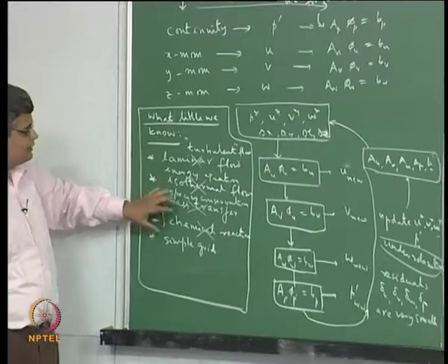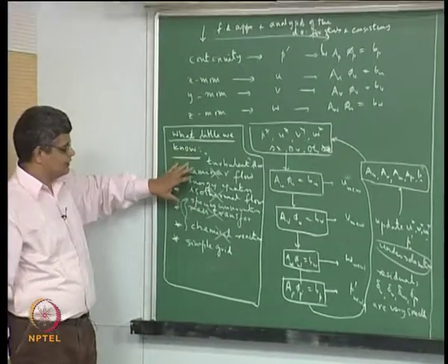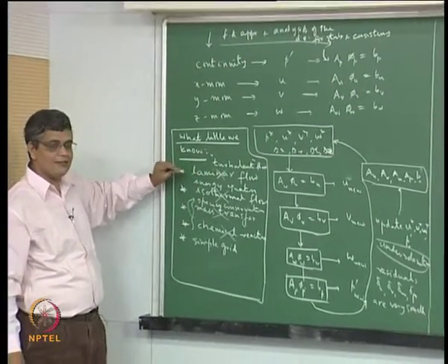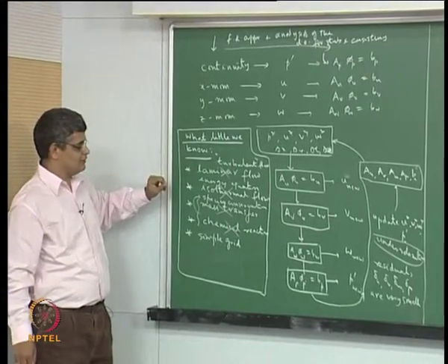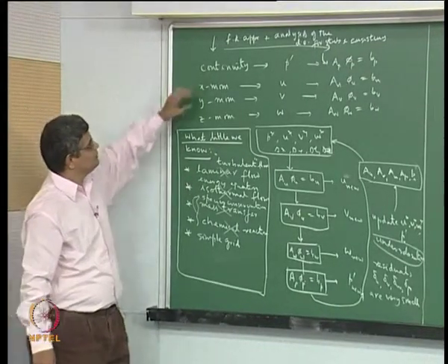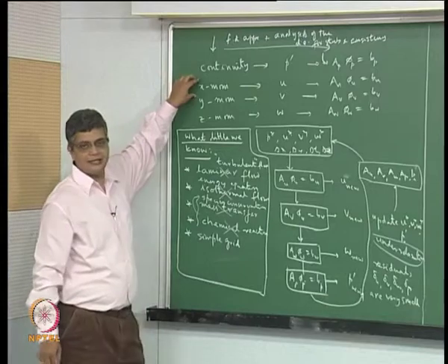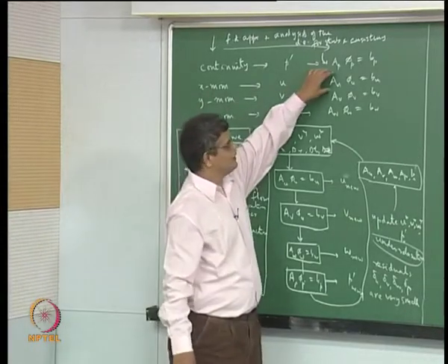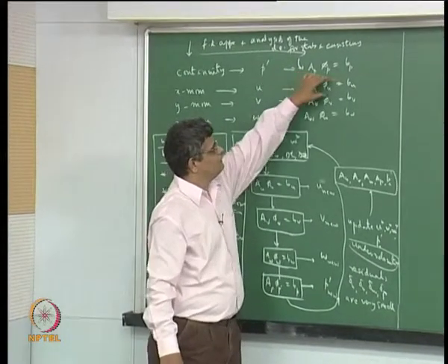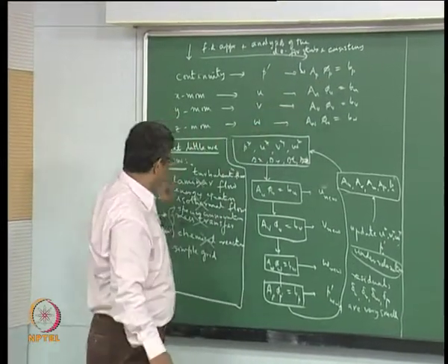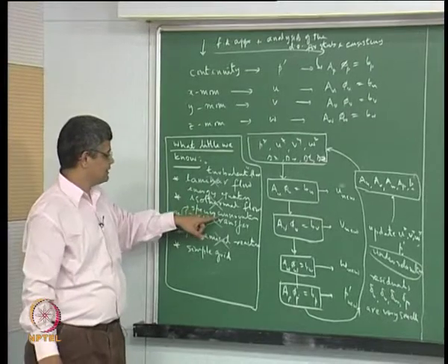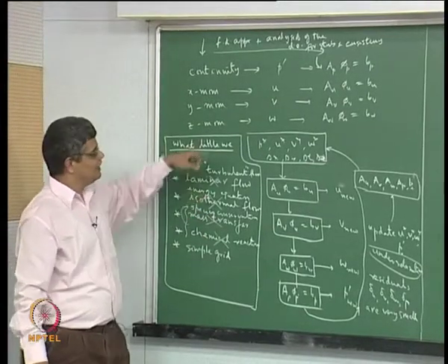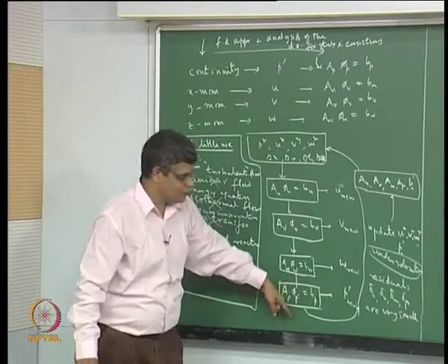We will see that each of these equations that are necessary to tackle these real fluid situations can be put in the form of the typical scalar transport equation, and therefore it can be readily converted into some A phi equal to B representing that particular equation, for example, the species conservation equation or the energy equation, and therefore it can be readily incorporated into this.